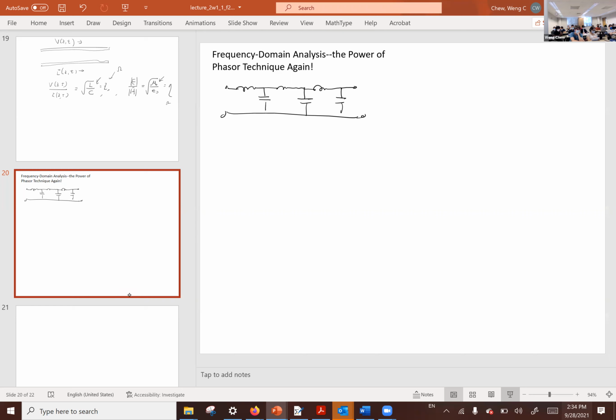We have current between the capacitor plates, and resistive loss in a piece of wire. So it is more appropriate to think that when we have resistive loss in a piece of wire, that wire is not just an inductor, but an inductor in series with a resistor.